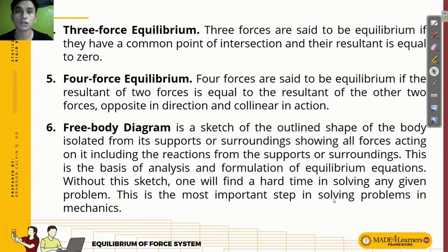As you can see in the past figures, you saw the applied forces, but some forces were not shown, which are what balance the body, the supports. The supports are the reaction forces. So when we make a free body diagram, we convert the drawing of the support into reactions. So we see the applied forces including the reactions. That is why it is called a free body diagram. By that, you can decide which equations to use to solve your reactions. That's why this is very useful.